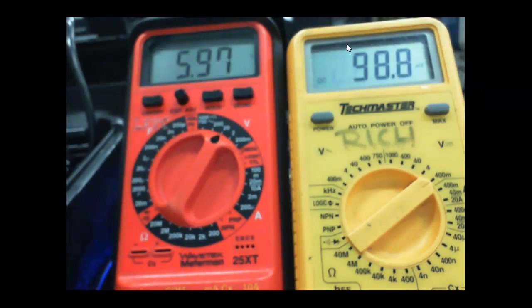No, it's not V out. That's the current. V out, where would I read V out at? Or across the Zener too, right? Okay, because the Zener's in parallel. So this is the load. This is the voltage right here. This is V out with V in minimum.